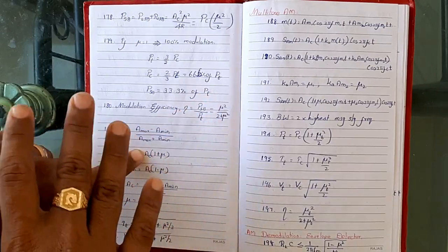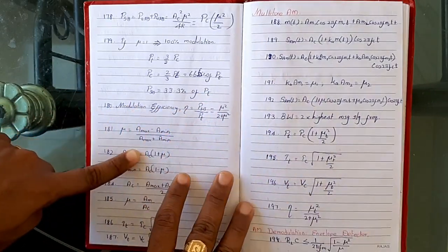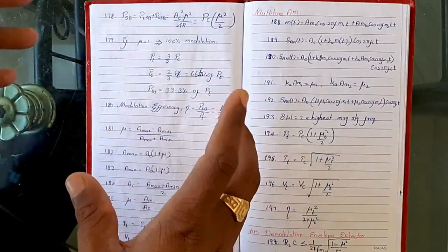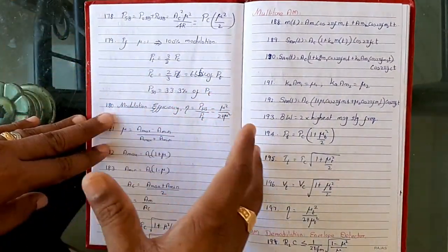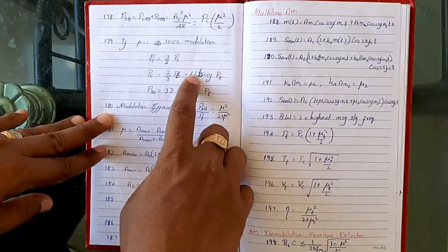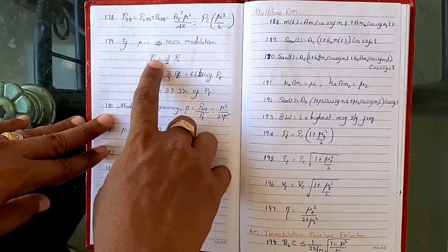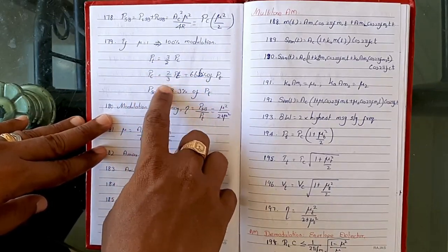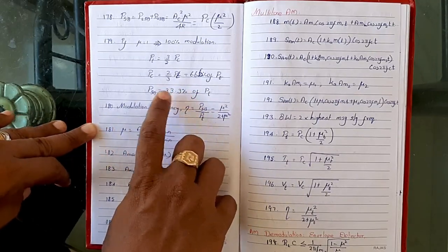So for an amplitude modulated signal, double sideband full carrier, the carrier is also involved, then the upper sideband and lower sideband, both are involved, and a lot of power is concentrated in the carrier. So a lot of the signal's power is carried by the carrier, 66.6%, and the remaining 33.3% contains the information in the sidebands.